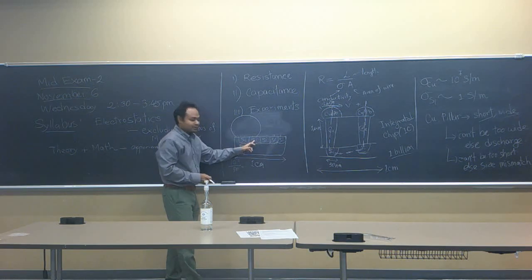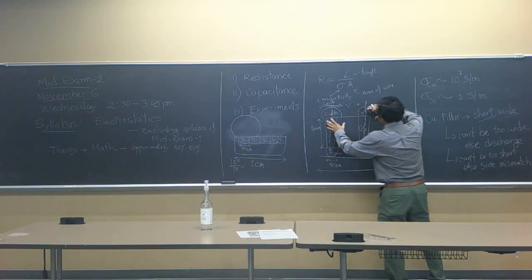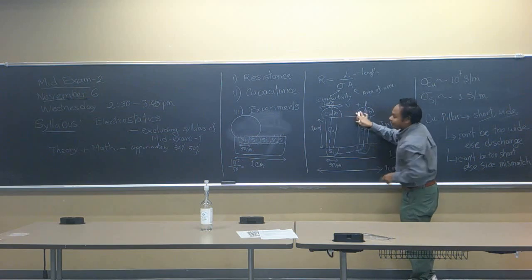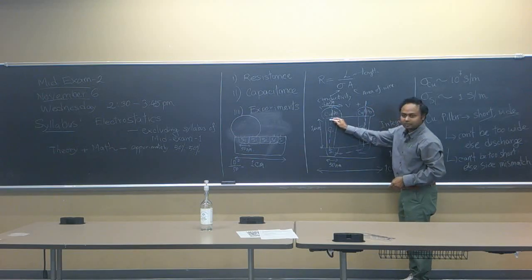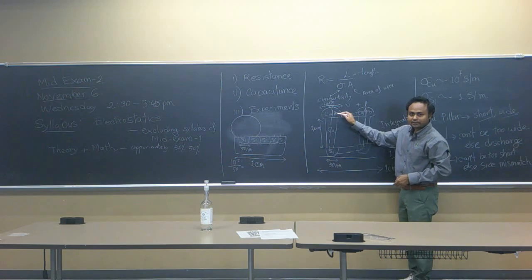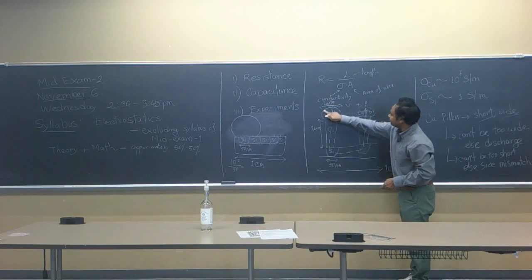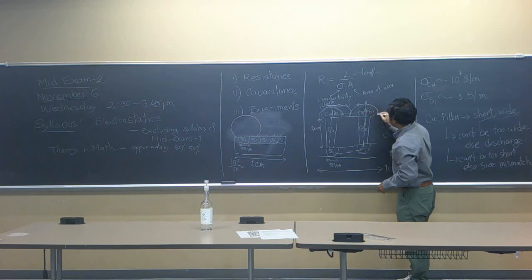Then these two silicon devices are not different, you're saying, right? Let's look at here. Let's say that I make this copper pad so big that they touch each other. Will the current go through this part, or will the current just go through here? The current will just go through here, right? So you cannot make this copper pad so large that they start to bump into each other.